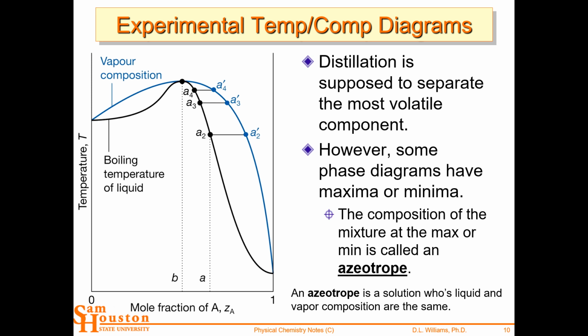But if you look at this, it's very similar to just two phase diagrams. So you could just draw this line right here, and that's the azeotrope. And so if I take a solution right here and I boil it, and I do fractional distillation, what's going to happen? It's going to boil. The vapor is here. The vapor condenses, gives me a liquid, which then reboils, which then condenses. And so pure A is collected. The lowest temperature substance is collected in the collection flask.